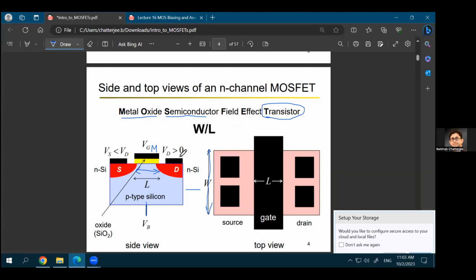Okay. Now, another thing that you can probably already relate to from whatever you have learned using op-amps is that if I'm applying a voltage at the input of the MOSFET, in this case the input is the gate terminal, because that's where you apply a voltage to get a certain amount of current between the two output terminals. So if you apply a voltage at the gate, you'll see no current flow into the gate.